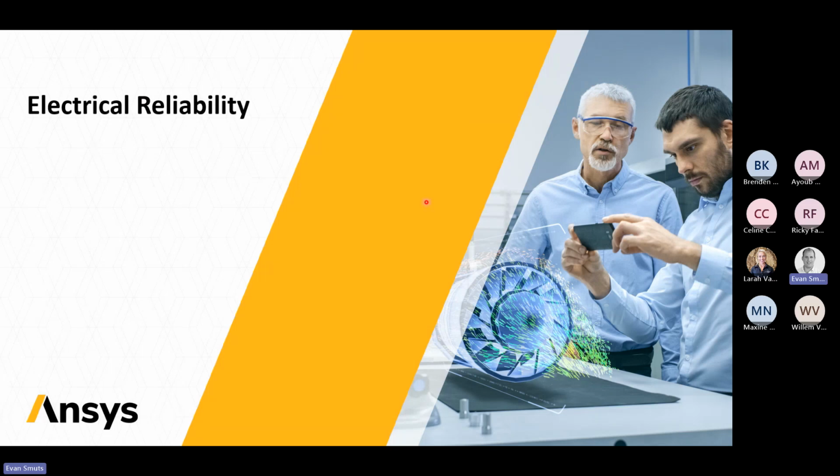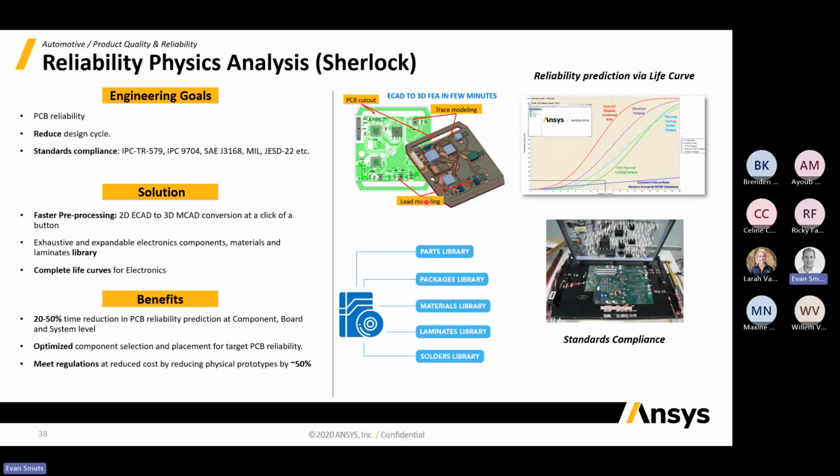Now we look more at the mechanical side of reliability. So this is where the influence of either thermal or physical shocks come into the PCB and the reliability prediction of that PCB. So, these environmental loads or these physical loads could be due to the operation of the components, either the current draw causing heating of the components, or from external environmental stresses.